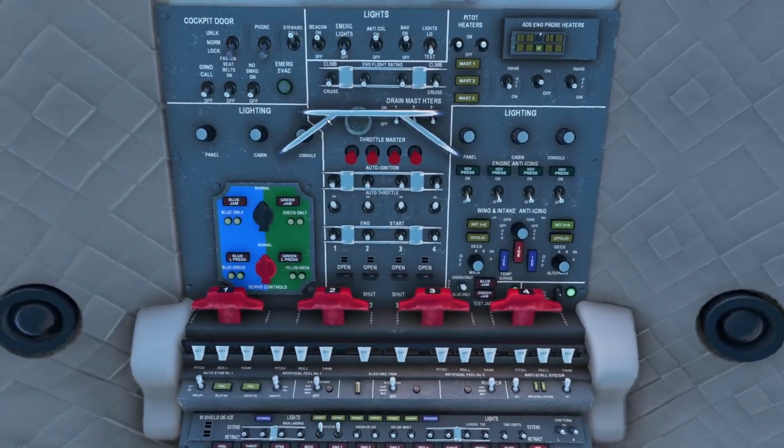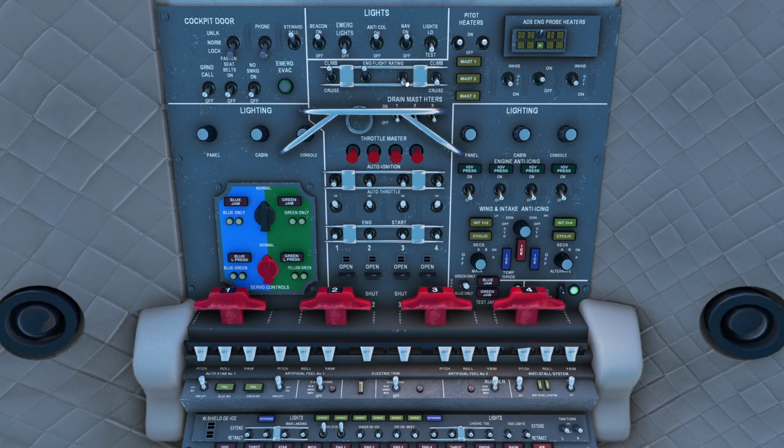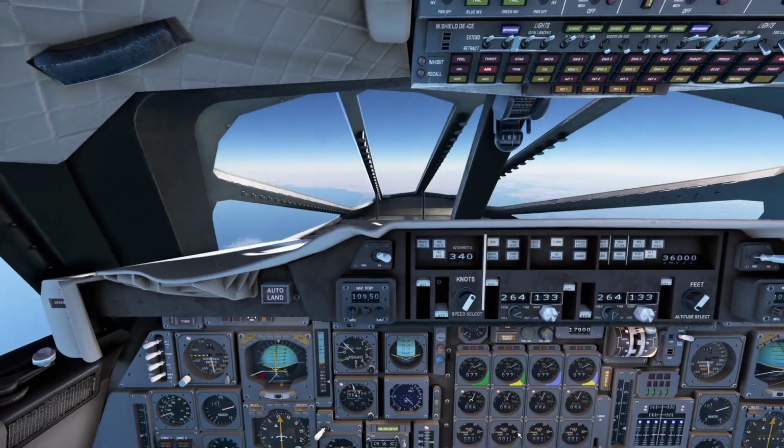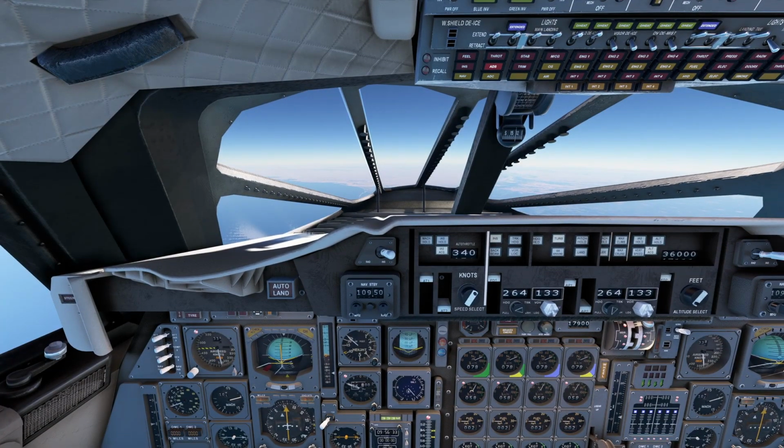We still need to change, we should have done that much earlier, sorry, to climb, doesn't change that much, and turn on our landing lights a bit early, but we have other things to do later on. Next little change, approaching 360, 340, gonna reduce speed to 325 and to flight level 240.